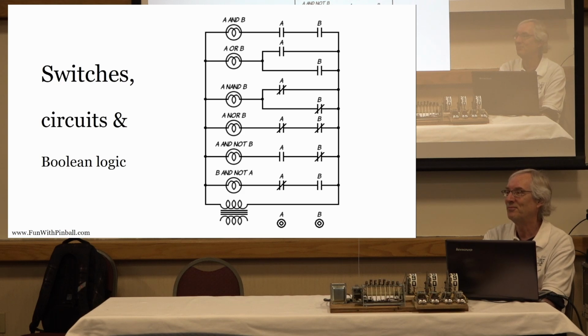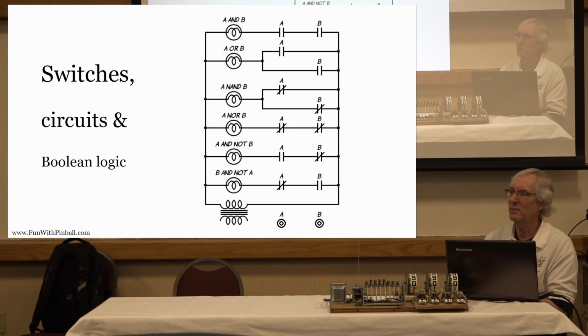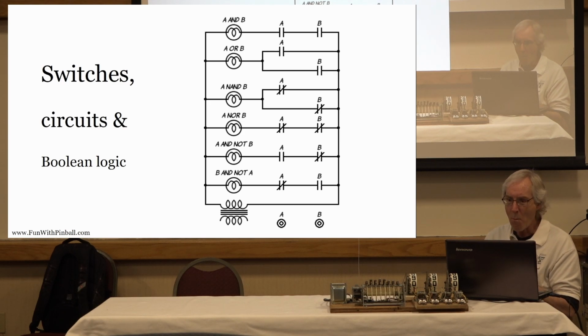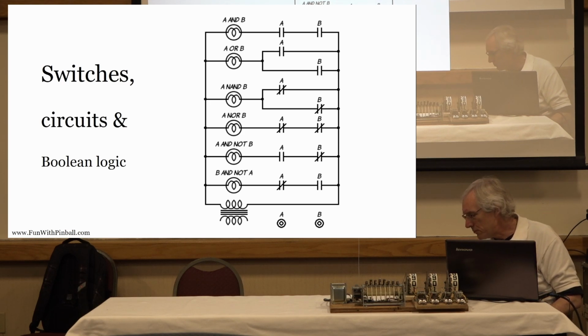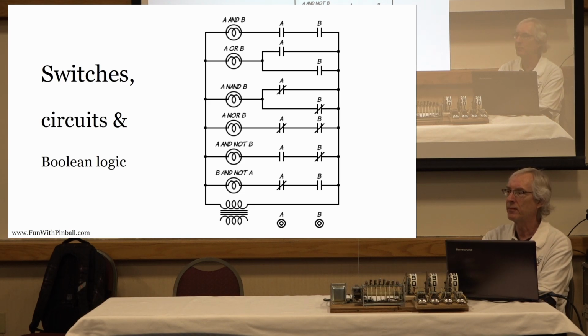Yeah, Gottlieb kept improving the mechanics of their score reel, even in the mid-70s, when they already knew solid state was coming, and they just kept making the nylon thing a little better, smoother acting, less likely to jam up, and the ratchets would have less wear on them, so they wouldn't wear out as quickly.